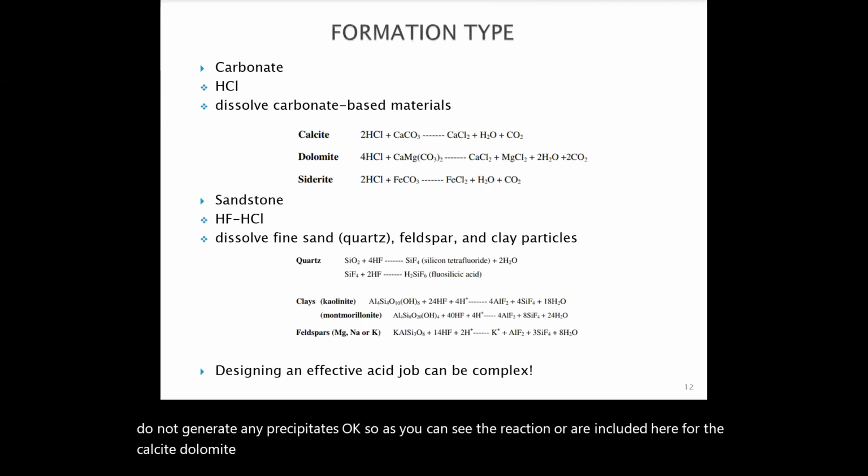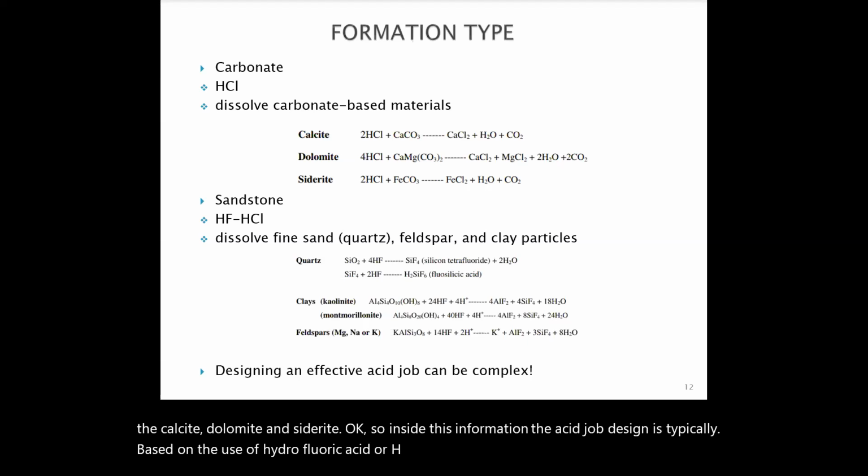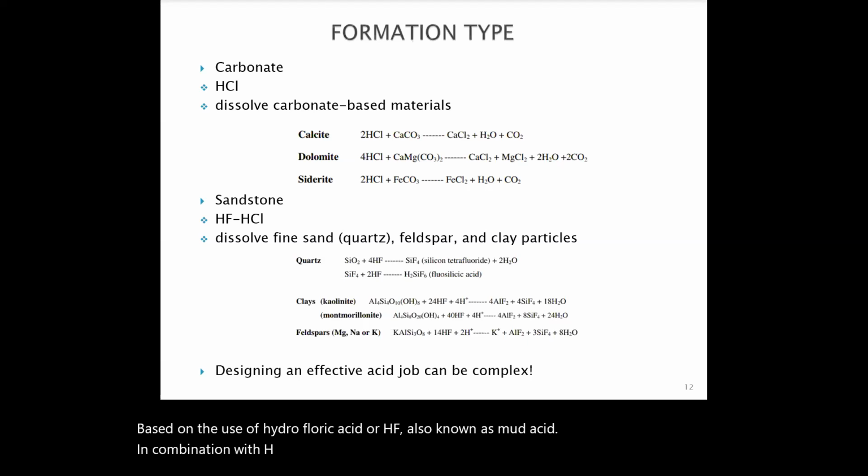In sandstone formation, the acid job design is typically based on the use of hydrofluoric acid, or HF, also known as mud acid, in combination with HCl. Sandstone materials are not appreciably soluble in HCl alone, but are much more so in mixtures containing HF.